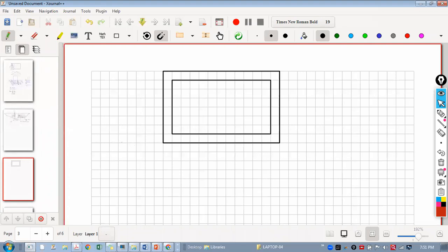And let's say this is a water tank level and the bottom level is also fixed. Say it is an on-ground water tank, which may be in a sewage treatment plant or water treatment plant. It is not necessary that we can lower this raft to the hard strata below the ground, because the level is decided by the architects or functional requirements. That means this is our water tank and the level is also fixed. And let's say we have a soft strata over here. So definitely, as it is soft, we cannot rest this structure on it, and then we will provide piles.